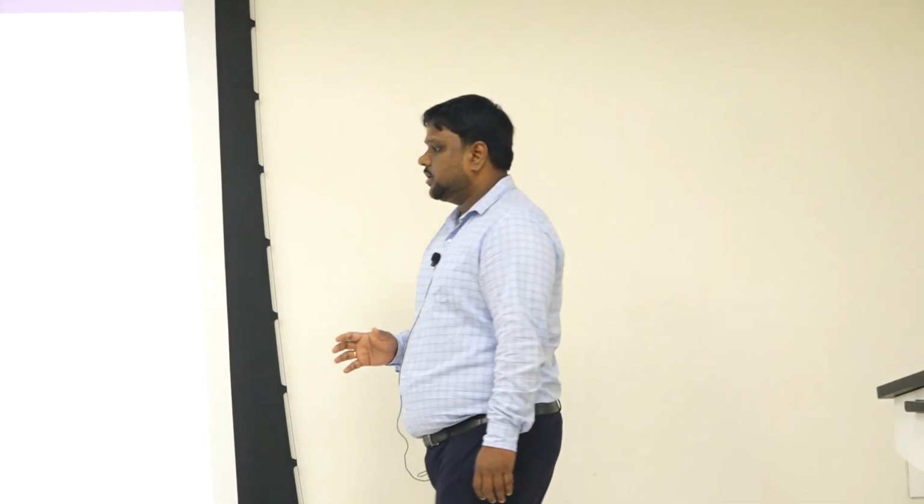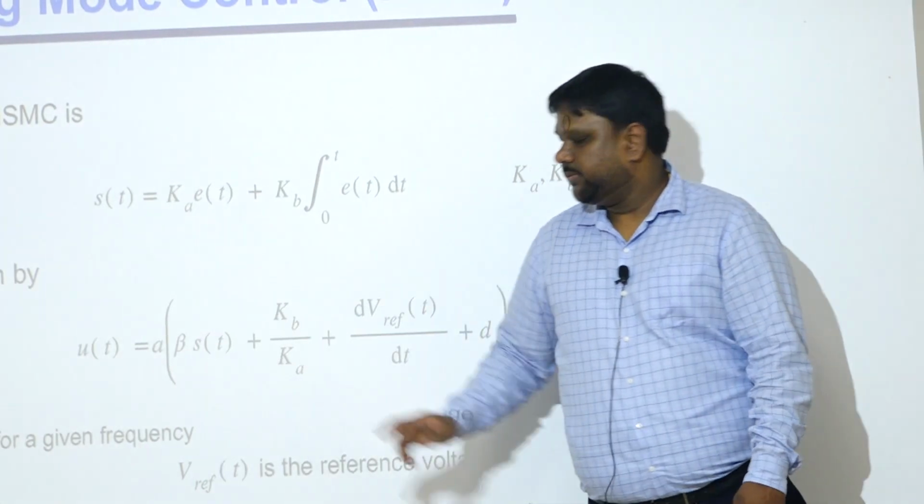So, this is your final control law which you will use to control your DC-DC buck converter. And here if you see, these gains K, Kb, alpha, beta all have to be properly tuned. For tuning purposes, as I told, you can use some kind of nonlinear control stability theory, let us say Lyapunov or whatever. If you can tune those parameters properly, it will ensure you have a wide operating range for your electrolyzer. It is no more directly affected by input disturbances.